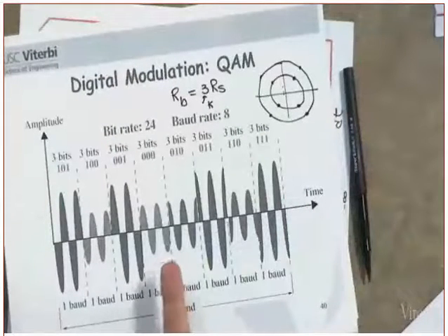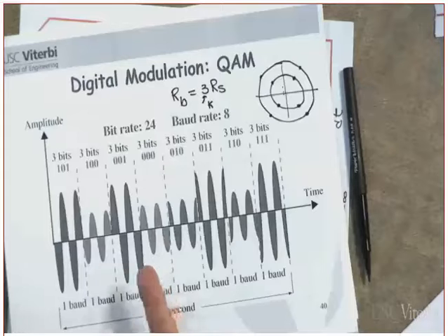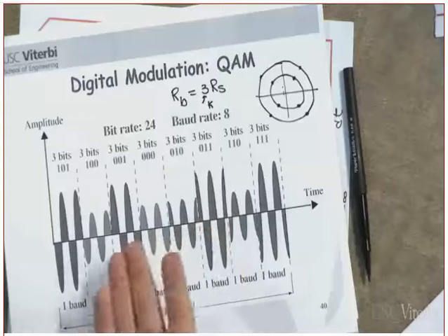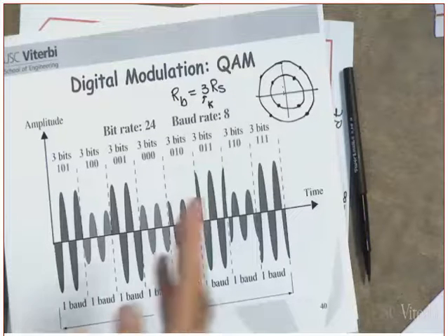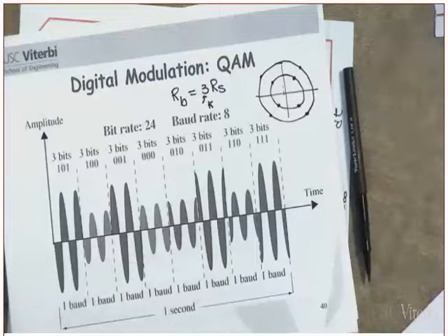Okay. By the way, constant envelope or non-constant envelope? This is very clearly non-constant envelope. Are you following me or not? We will see later on that these are more bandwidth efficient than constant envelope modulation, like the GMSK or the MSK. However, this one would require the power amplifier to operate in a linear region. Are you following or not?